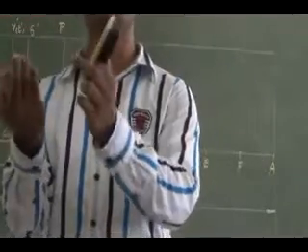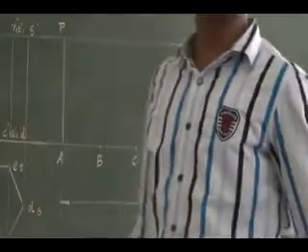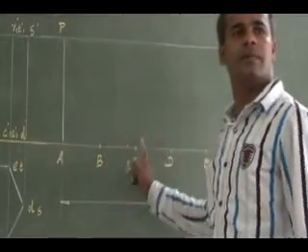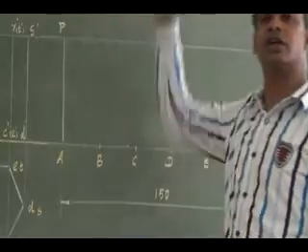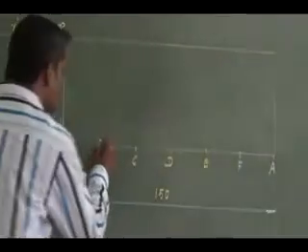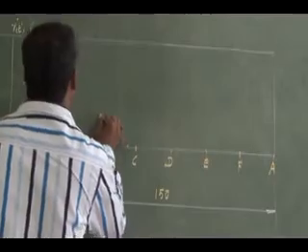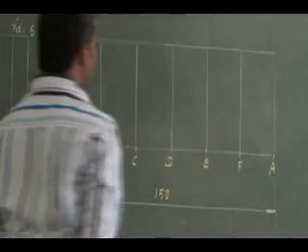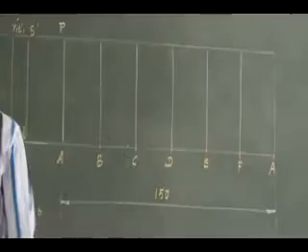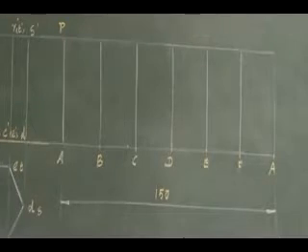Then I have to show the vertical edges where I am going to fold it. So these locations are B, C, D. That is the location I am going to have my folding, so that location also you have to show as an edge. If I fold these edges at the appropriate location, I will have a hexagon.